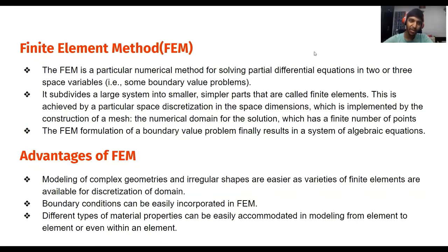First things first, let's talk about what the finite element method is. The FEM is a particular numerical method which is used for solving partial differential equations in 2 or 3 space variables. It subdivides a larger system into smaller, simpler parts that are called finite elements, probably where it gets its name from. This is achieved by a particular space discretization in the space dimensions, implemented by the construction of a mesh. Mesh is the numerical domain for the solution, which has a finite number of points. The FEM formulation of a boundary value problem finally results in a system of algebraic equations.